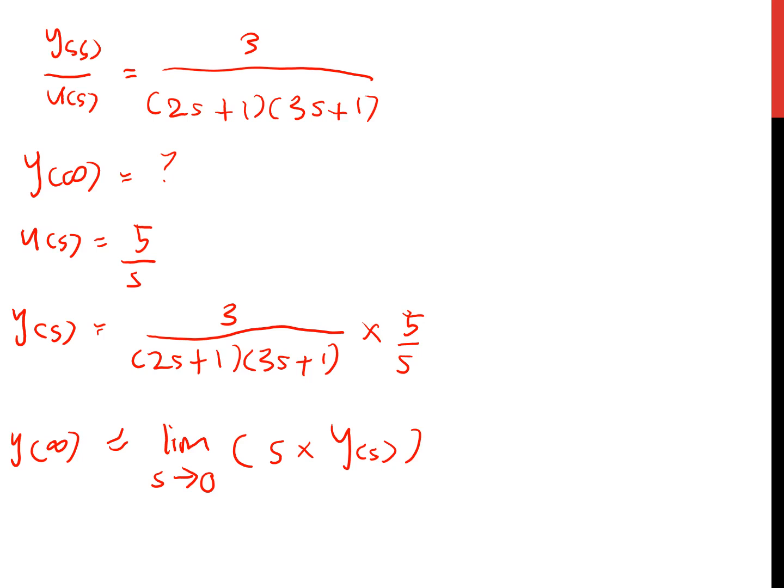So this equation is multiplied with s. When you multiply with s, automatically this will be cancelled. Time infinity, s equals 0, so this term becomes 0. This means the answer will be 15. So without using the inverse Laplace, I can know the final value of the given equation is 15.